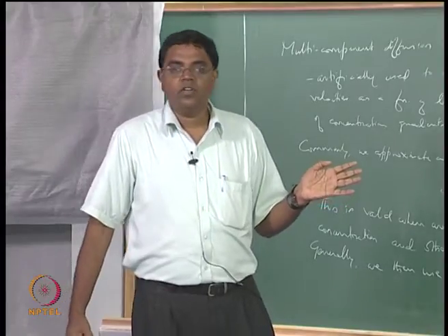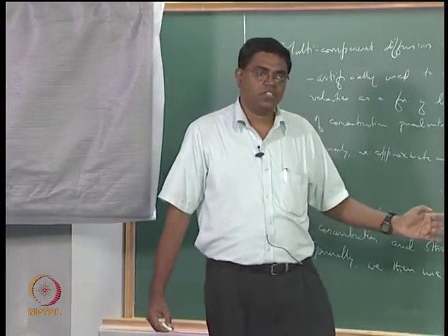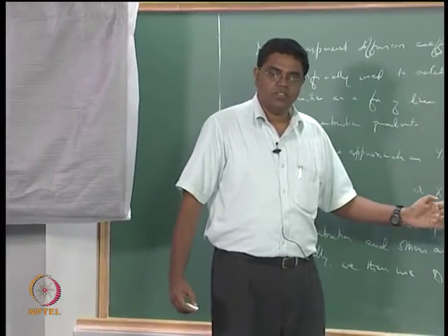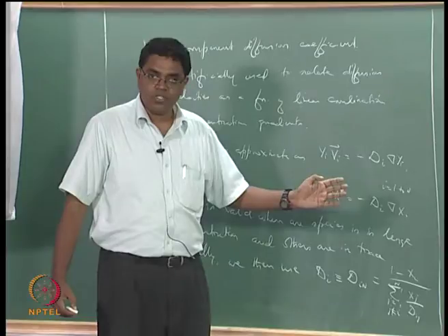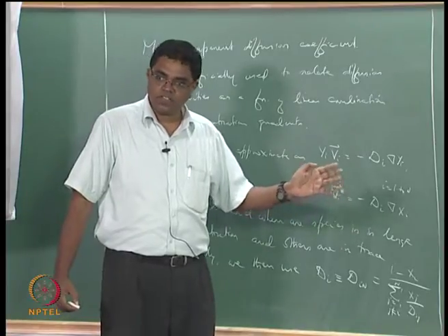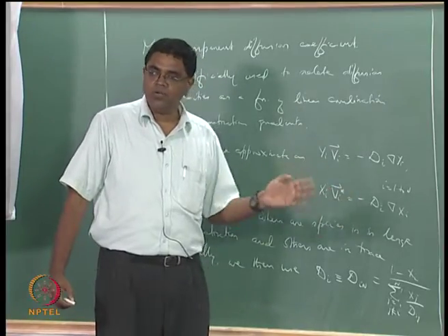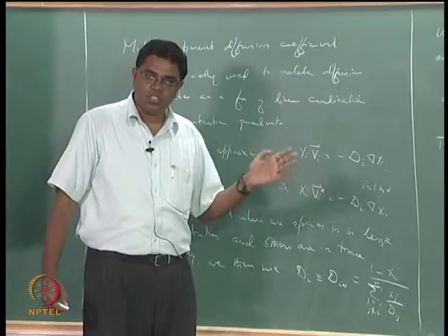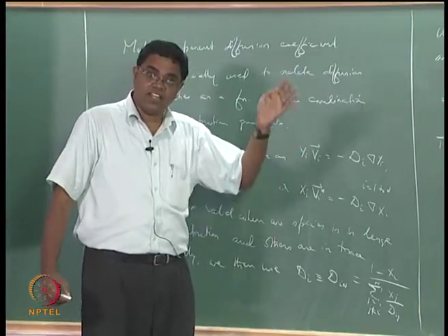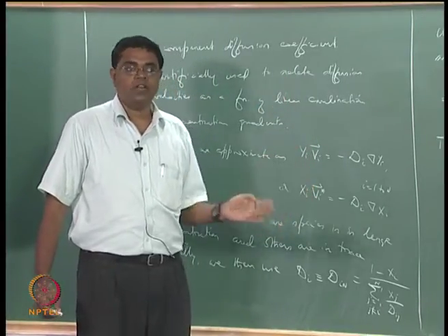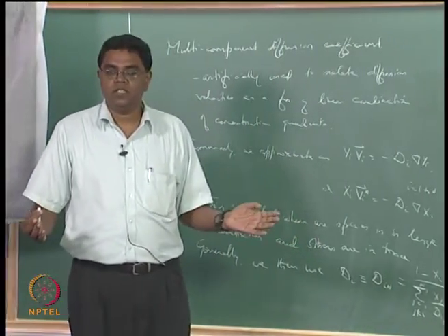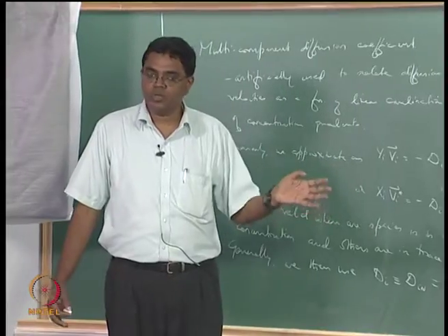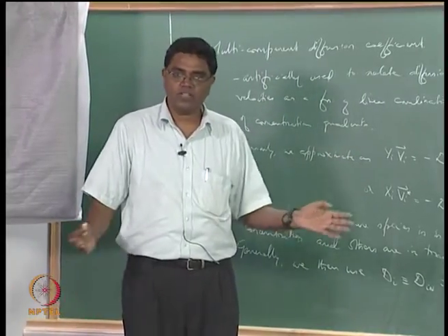We have not shown this in these lectures for the multi-component species conservation equation, but I would like to leave it as an exercise for you to go back, look at the multi-component species conservation equations and add them up to show that even for a truly multi-component system you should get the overall continuity equation to be like a single species non-reacting situation.